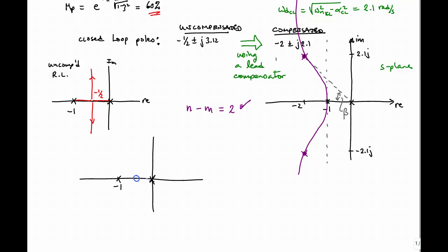Now my root locus is going to lie to the left of the pole at 0. It will not lie to the left of this 0 that I've placed, because there's an even number of poles and zeros to its right, but there will be a root locus to the left of -1, because to the right now are an odd number of poles and zeros. So this is what the root locus would appear as.